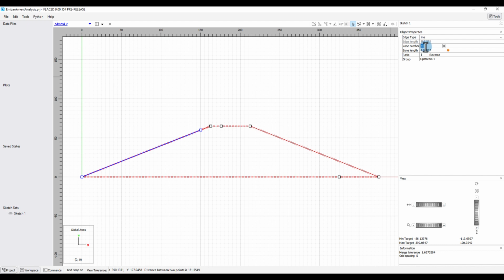For this analysis, an unstructured mesh composed of only quadrilateral zones will be used. For this to be achieved, go to Meshing Parameters and then select Create Unstructured Mesh Only and Use Only Quads in the Unstructured Mesh.